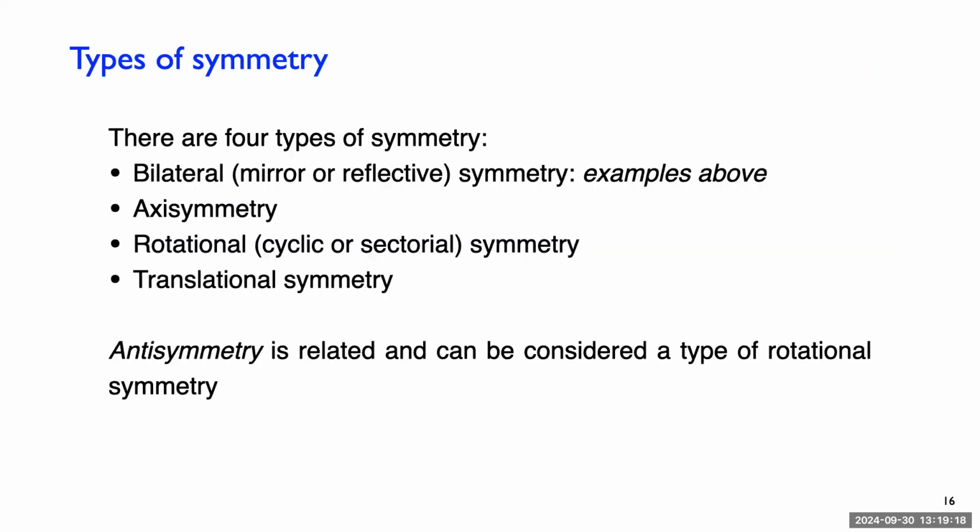So one thing to point out on that symmetry, on that buckling and that flow problem: if you model that with a symmetry condition, you will get the wrong answer. You will get a symmetric answer because you're forcing symmetry on a solution that doesn't want symmetry. So you have to be careful when using symmetry.